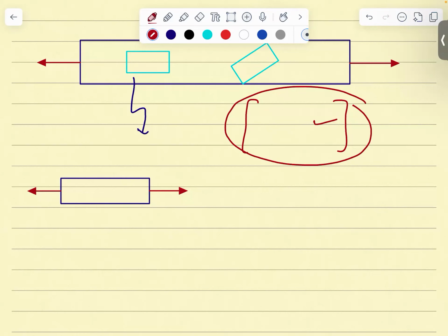So every time a problem is given to you, the first thing is you should note what the state of stress is. If you are able to figure out the state of stress at a point in a body, your problem is solved. We have to identify what kind of stresses are acting. Then you can transform those stresses. Then you can find what is maxima, what is minima. I will show you in a while how to find maxima and minima. Is it okay?